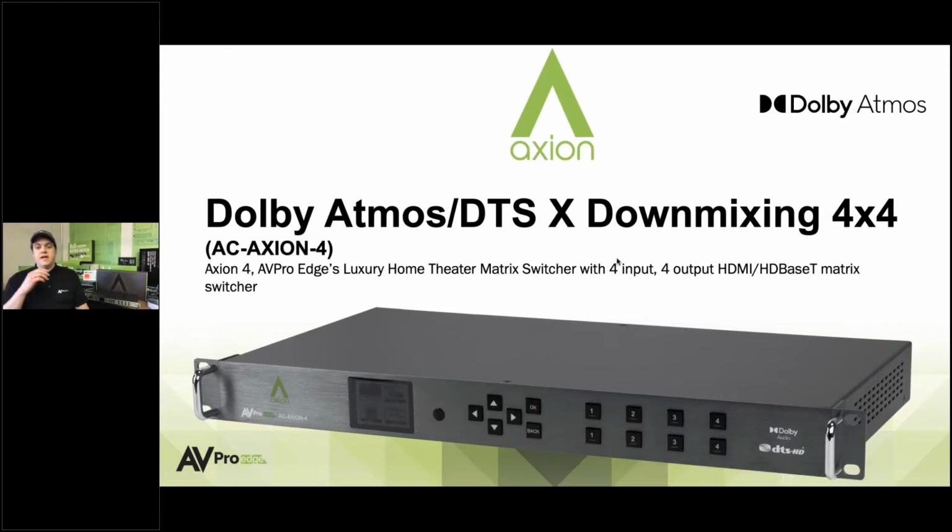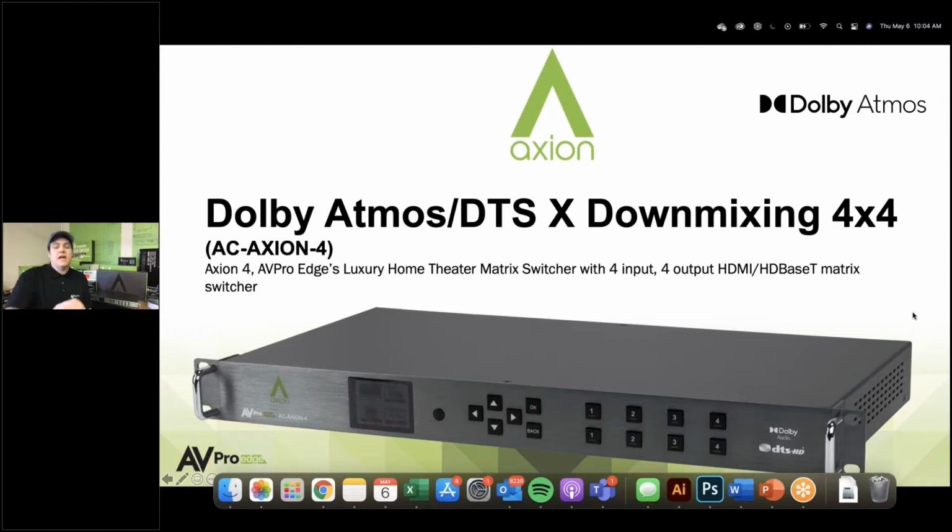So this is a Dolby Atmos, that's a sound codec, DTS:X sound codec, downmixing 4x4 matrix switcher. It has 4 HDMI inputs. It has 4 HDMI/HDBaseT matrix ports that are mirrored, so you have both ports in the back and they're both active at the same time, allowing you to use both of them. But it is the classic 4x4. This is what you're going to see here.